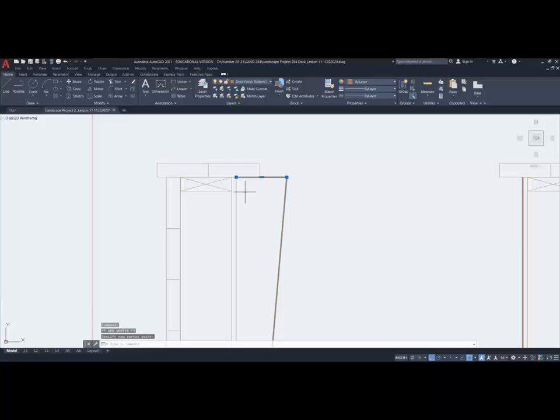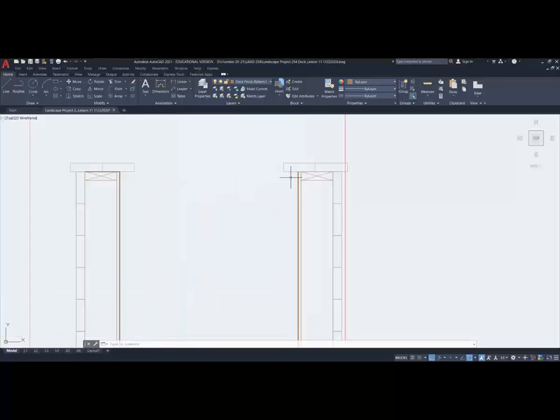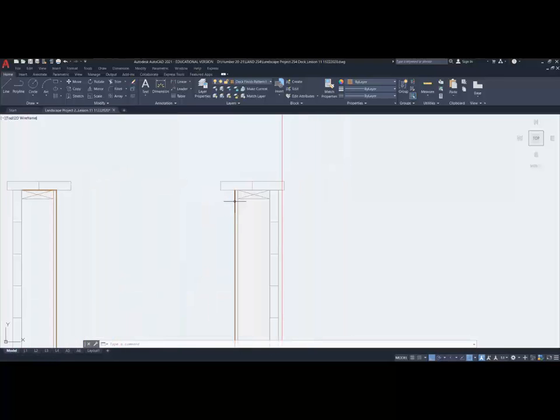And you can see what it's trying to do. I can then run that rubber framing or membrane underneath there and run it on top of there. Now, when I actually go to secure this top ledge, I'll be going through the rubber membrane, but that's okay. It can leak at that point because the soil and the water won't be that high. So that's perfectly fine.